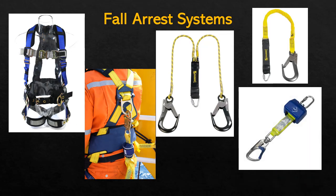The type of lanyard you see here is another type of shock absorbing lanyard, but this one works more like a safety belt in a car in that when you're walking, you can keep pulling out a little bit more of the reel, so you can get a longer lanyard. But then once it senses a sudden jerk, it locks up. So just like a safety belt in a car, these are designed so that if a person, say, trips and falls over, it automatically freezes up, so nobody gets exposed to more than just a person-height fall. So these are the types of systems you see.